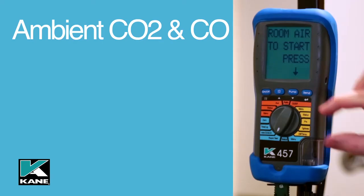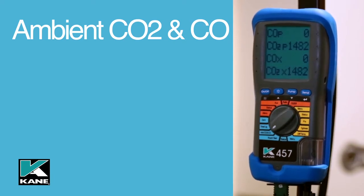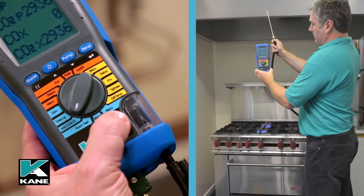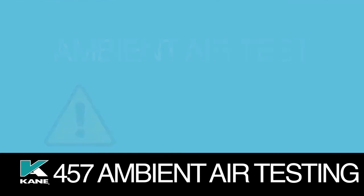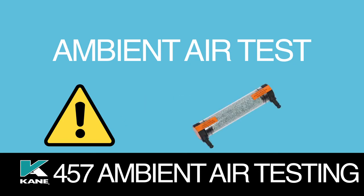By selecting the next function on the rotary dial, Ambient CO and CO2 allows you to monitor real-time and maximum CO and CO2 levels, and could be used by commercial catering engineers when monitoring ambient levels of CO2 in ppm, parts per million. Note, before carrying out this test and to ensure accurate ambient measurements of CO2, the KANE457 should always be zeroed using a zero cal capsule. We shall demonstrate this in a few minutes.